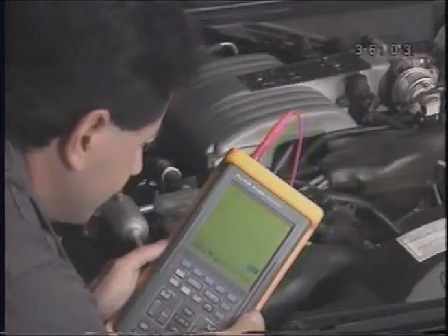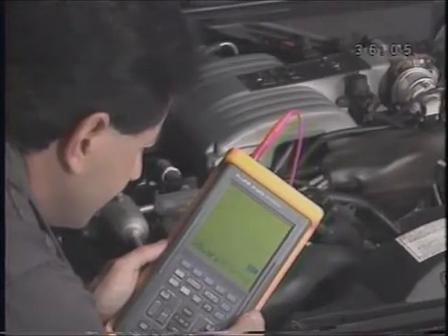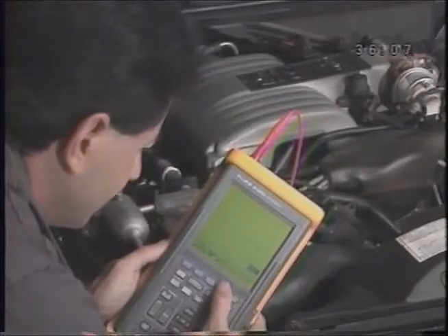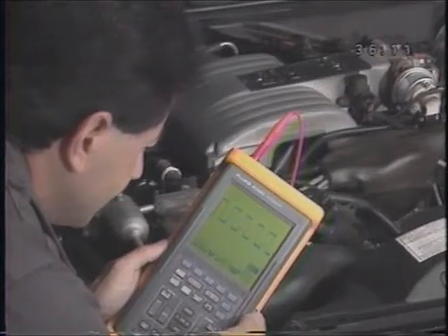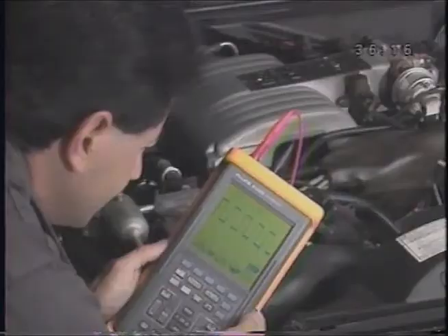Sometimes a sensor or circuit can experience a momentary glitch or signal change. Press the min-max soft key. Scopemeter's 40 nanosecond glitch capture and min-max feature increase the sampling rate to its maximum level, making Scopemeter capable of capturing and displaying a glitch as short as 40 billionths of a second. The question is, will you be watching the display when that glitch shows up?